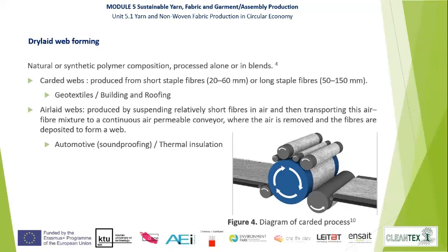The air-led webs are produced by suspending relatively short fibers in air and transporting this mixture to a continuous permeable conveyor where the fibers are deposited to form a web. And this web is mostly used in automotive as a soundproofing or as thermal insulation.